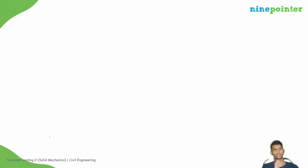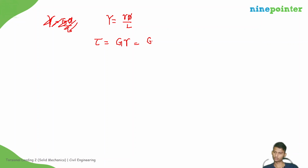Let us summarize the whole thing. First, we got shear strain gamma. Sorry, shear strain gamma is given by r phi by L, right? And from that we get tau is equal to G times shear strain, that will be equal to G r phi by L, right? And we derived the torsional formula phi is equal to TL divided by GJ. Okay, these are three relationships.